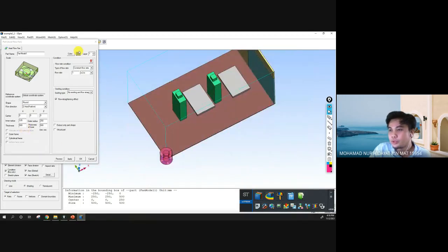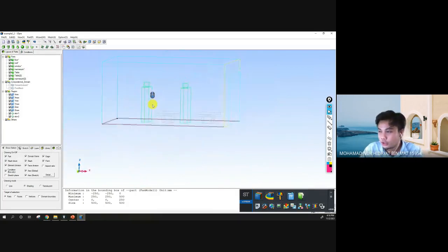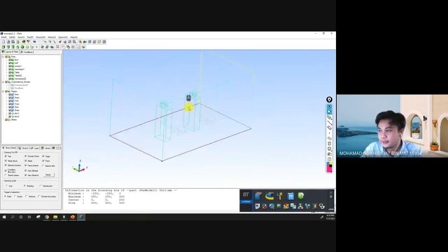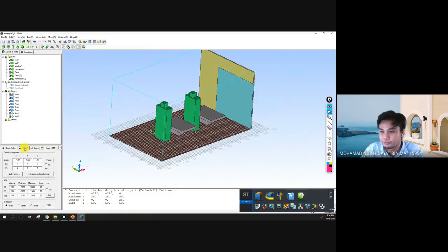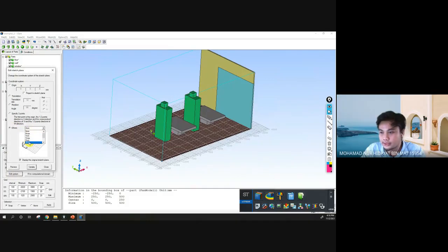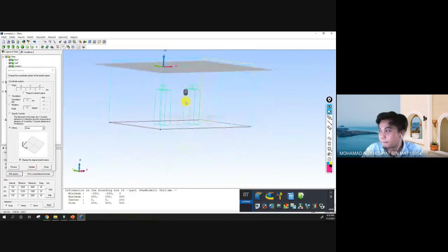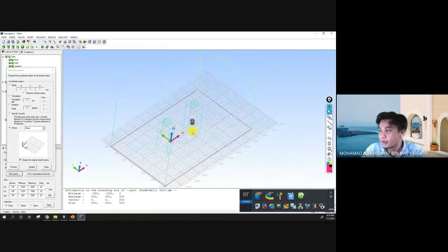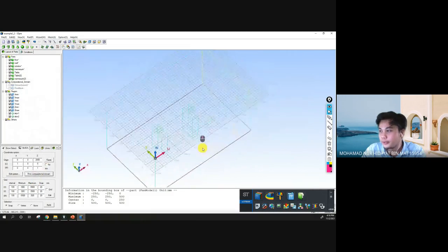So my advice, you want it on the top of the ceiling, right? Go here, sketch, edit system, X, go to the Z maximum, update, close, and fit to the computational domain.